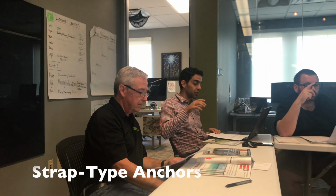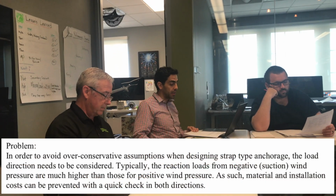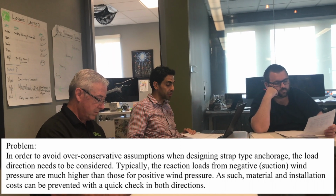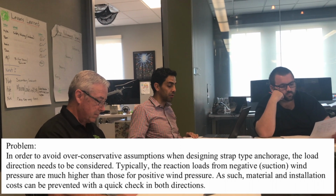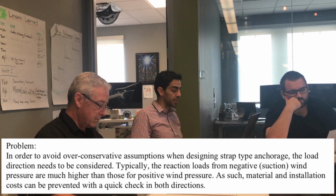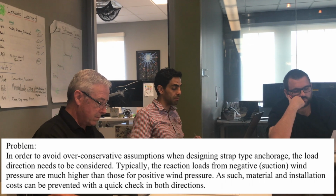All right, so this is following up what Stuart mentioned last week about the positive versus negative anchor analysis. When designing strap type of anchorage, especially typically at the head, the load direction needs to be considered. Typically the reactions from negative suction wind pressure are much higher than those from positive wind pressure, and as such, material and installation cost can be prevented with a quick check in both directions.